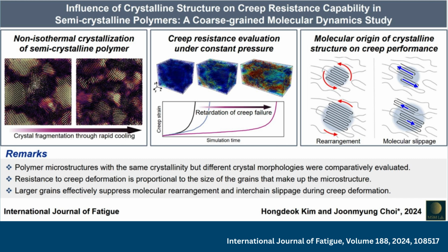Long-term mechanical performance is particularly sensitive to tie molecule connectivity. Slow crack growth in PE, for example, is strongly influenced by molecular weight, crystallinity, lamellar morphology, and intercrystalline tie molecules. These relationships are important for pipes, films, containers, and other applications requiring long-term durability.